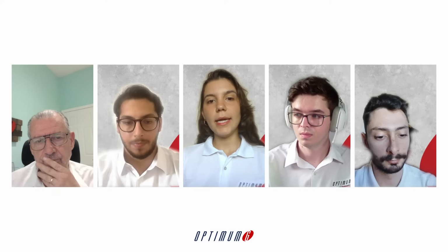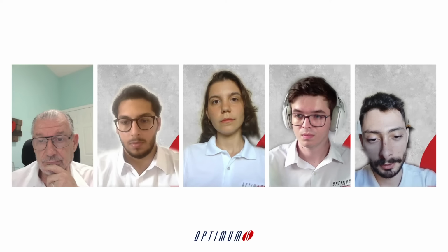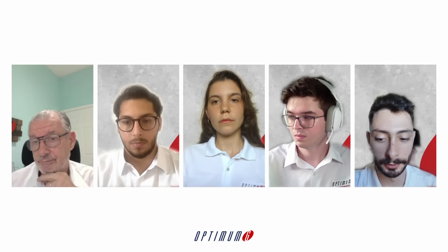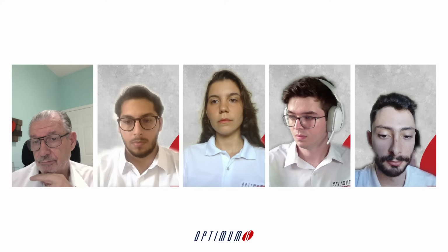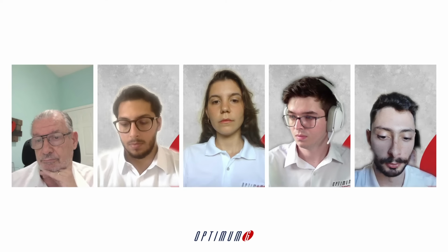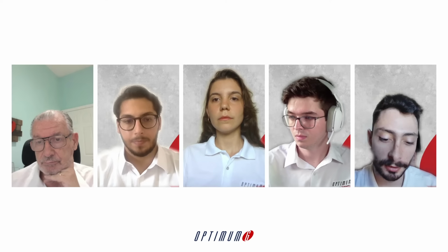Yeah. Thank you, Claude. Our next question is how we can find optimum camber and camber gain by skid pad optimization. Well, the skid pad optimization software that we showed you earlier, one of the things that it's trying to achieve is to find what is the optimal camber for every different turn radii that we're evaluating for that car.